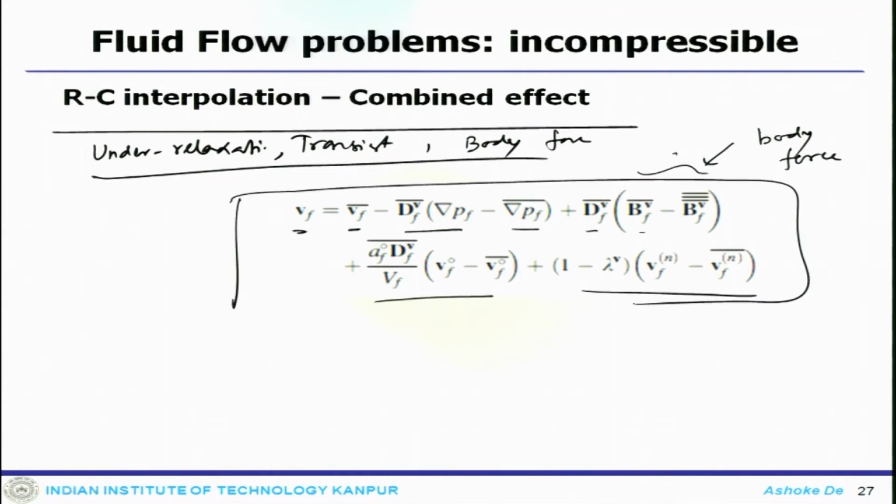So, this is how one can look at the interpolation scheme in this kind of system. Now, having said that, that pretty much takes care of the discussion on the incompressible flow. Now, we will extend a similar discussion where you can also obtain the pressure correction equation for compressible cases.